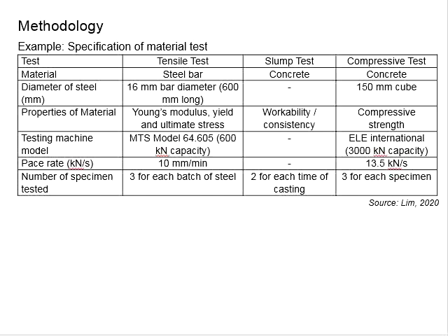The differences may be the degree of compaction and slight variations in the curing method. Unless you can find a better way to represent the strength of the beam specimen, testing the concrete cube or concrete cylinder is commonly used by the typical researcher who is testing concrete samples.